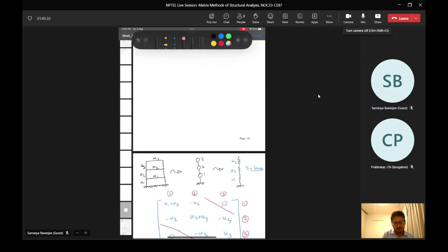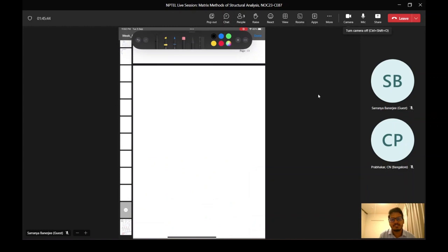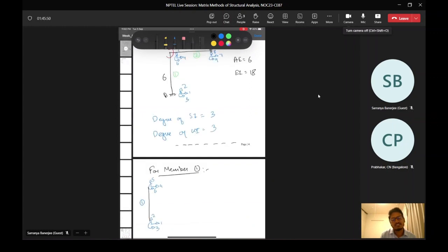So when we are talking about multi-storied buildings, it is kind of different masses in series as we go on. So these kind of banded matrices give us that checking option, and there are also other parts which we'll not go into right now. They tell us about the interaction between the different degrees of freedom also.